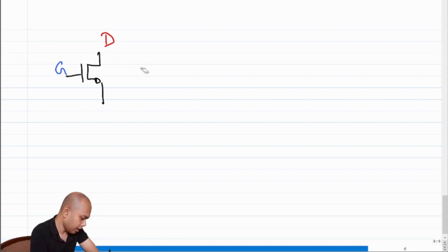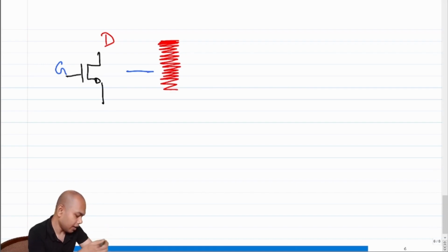Let's say this is the gate voltage that is fixed, and let's say the threshold voltage is positive, which means the drain voltage can go as low as 1 threshold voltage below the gate voltage. So for saturation, if you go below this, it will be linear.